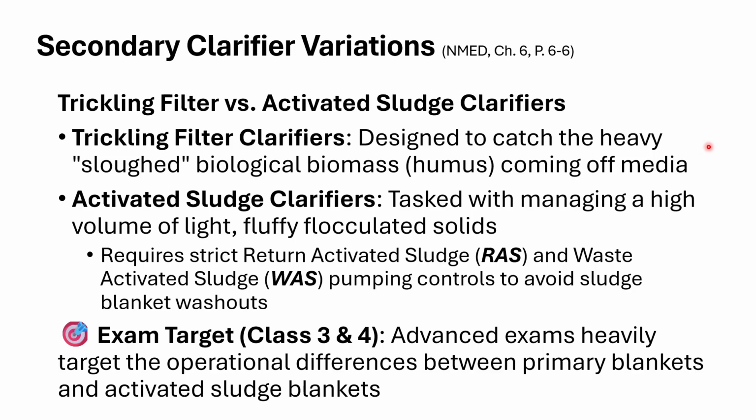We want the wastewater flowing over the filter media, and it's got what's called this heavy sloughed biological biomass or humus, and it's on the media. And that's where the microbes that are going to digest the waste and metabolize the waste are hanging out. Think of it again as a bunch of big rocks or medium-sized rocks in a filter bed covered with this organic slime. That organic slime has the biomass that is metabolizing the waste. And as we pour that wastewater over it, that's what that biomass is doing, okay?